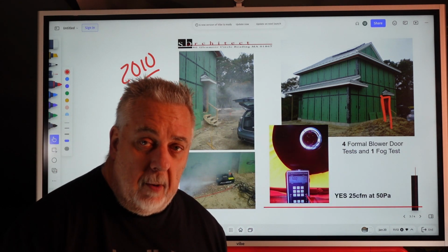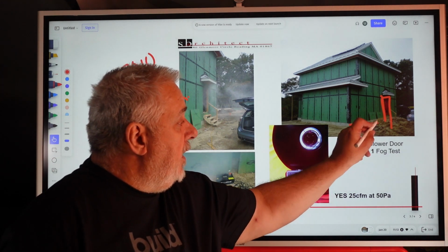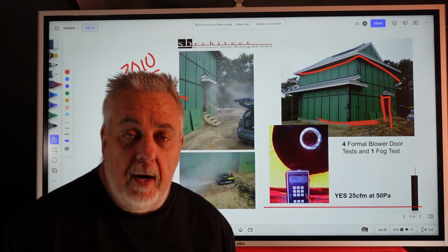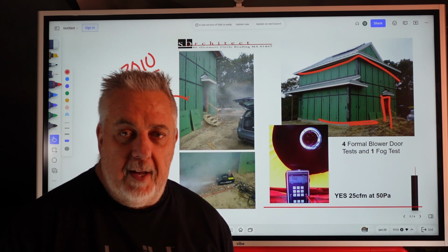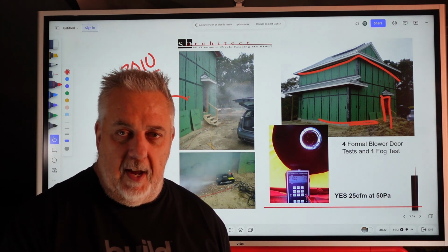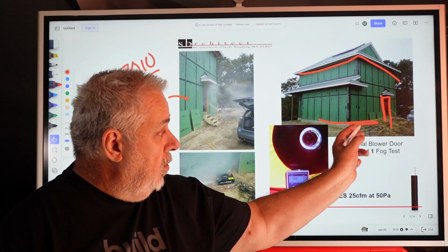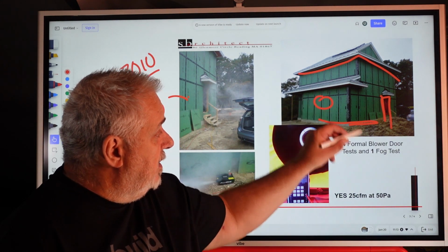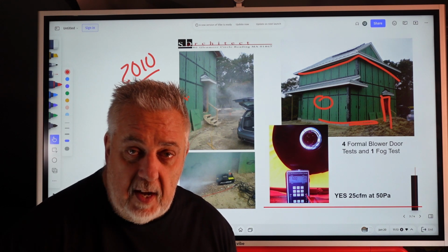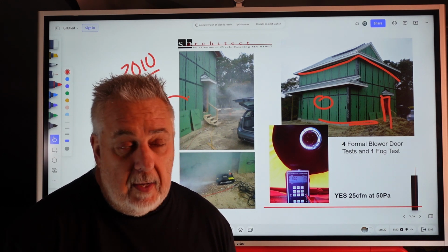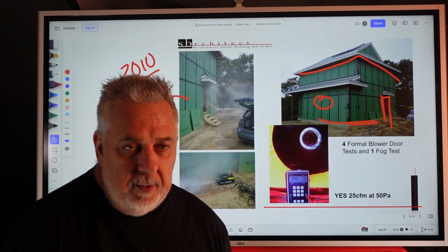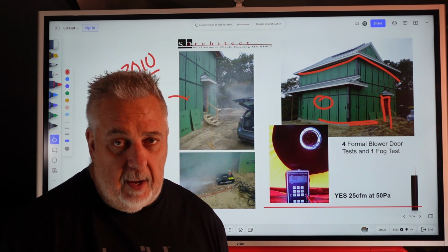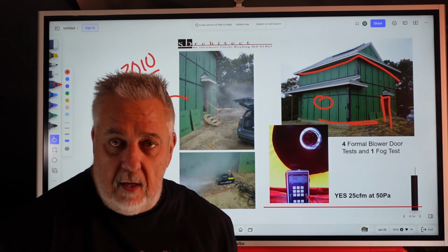Remember, Zip is our primary air barrier. So our slab was already in place. We had our drywaller come and put the ceiling in place now that the roof was on. And now we can do a blower door test. And not only is it a blower door test, but because the gypsum board and the foundation are already in, what we're really testing is the validity of the Zip as an air barrier. And yeah, it came in at like 32 CFM of total air leakage there. I mean, the number was crazy. I mean, it was probably like 0.16 or something like that.